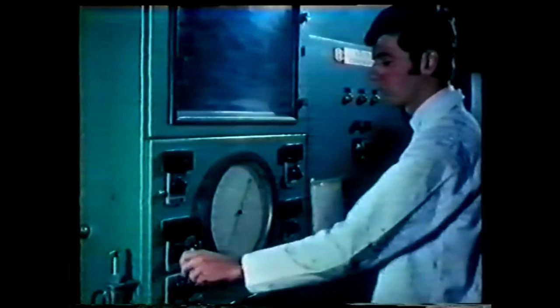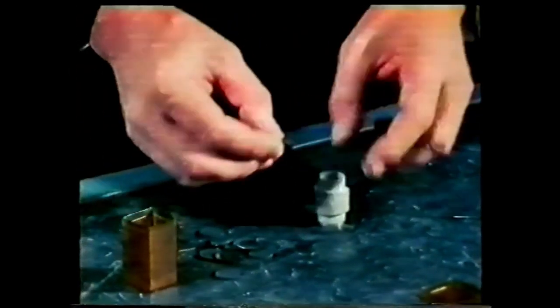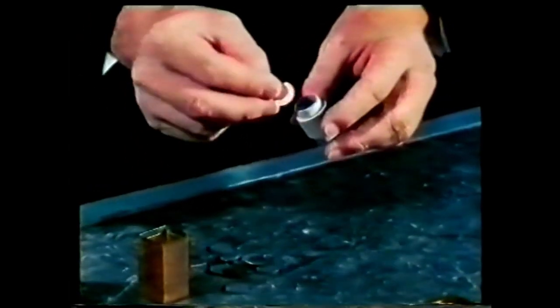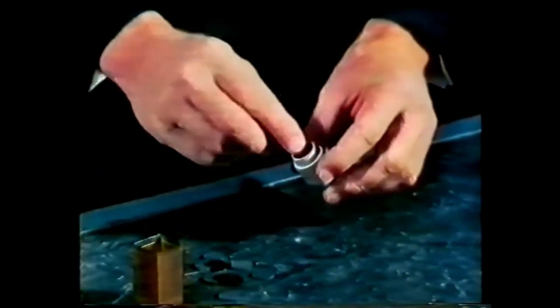Synthetic diamonds are made by simulating the conditions that once created natural diamonds. Years of research has gone into the development of equipment capable of producing pressures of 1 million pounds per square inch and temperatures up to 2,000 degrees centigrade. The basic ingredients for the process are these discs of graphite, which are loaded into a capsule interspersed with discs of transition metal alloy. The exact nature of the alloy is a carefully guarded industrial secret.